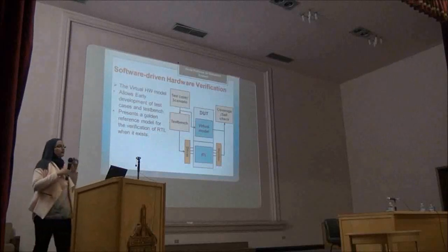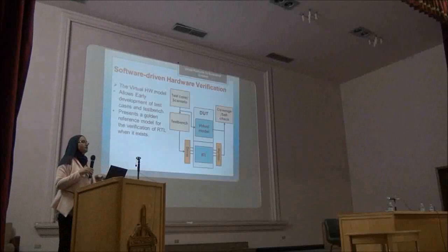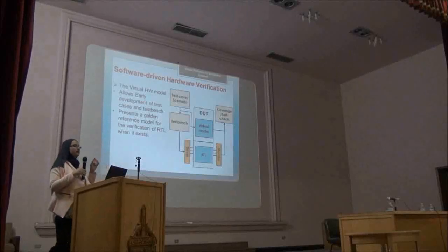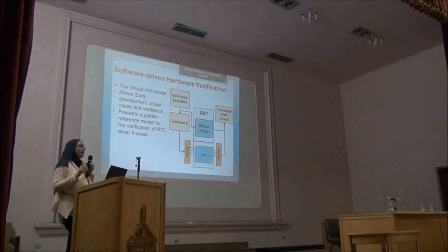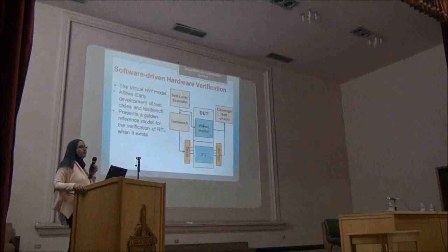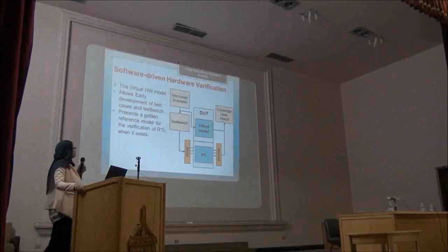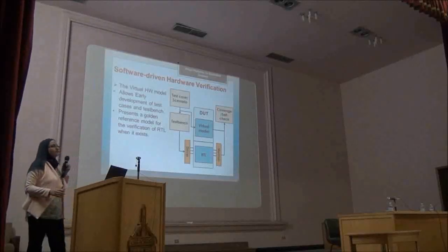Not only does a virtual platform help on the system level integration and on testing a complete system on chip, but it can also help in testing individual IPs. What if I started to develop the RTL of an individual IP? I can put it in a verification environment where the virtual model acts as a golden model and the RTL model is the model under test.